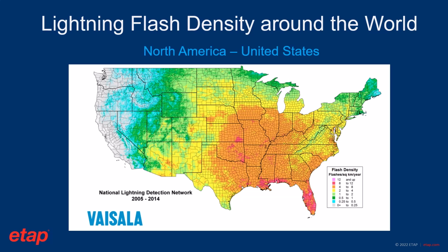And there are many ways to assess this in terms of the structure of the equipment, and in terms of the actual roof type and the corresponding construction of the equipment itself. So the lightning risk assessment calculation methods are basically calculated based on the equivalent collection area, which is mentioned in the NFPA 780 and the IEC 62305.